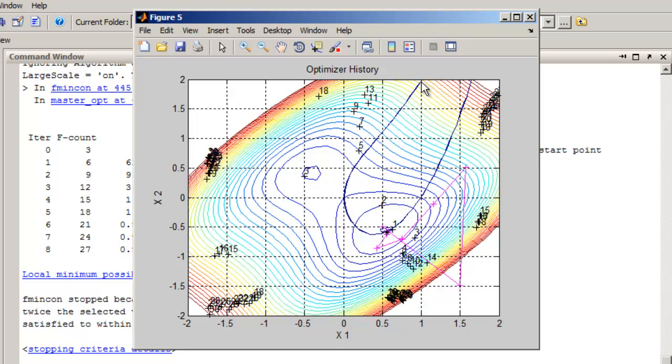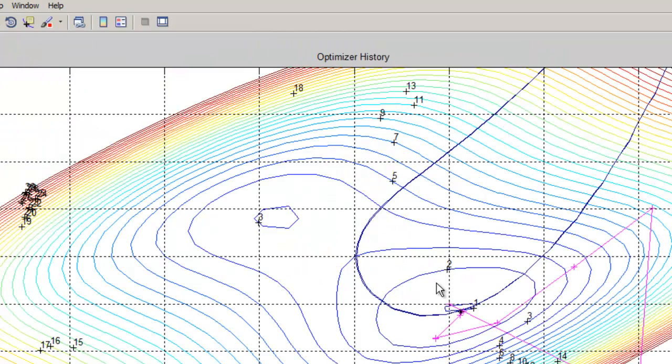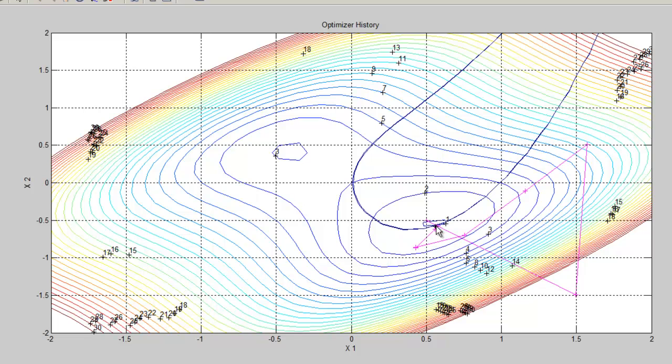And I want to indicate something here. You see this loop right here? This loop is the constraint. The way I define the constraint is that everything inside this loop, in this area here, is in the infeasible regime. I started my design infeasible, it skipped out, turned around, and came very close to that point here that I'm talking about.